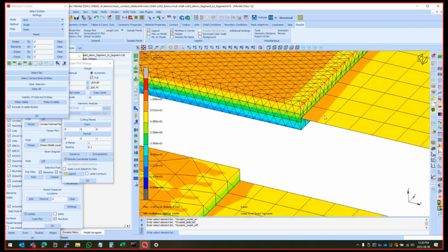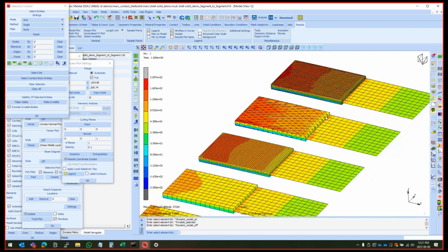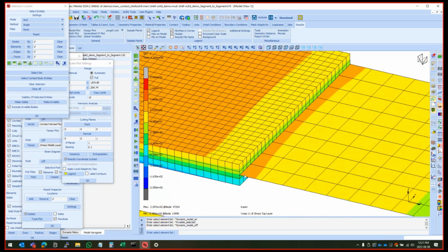For these second orders, I won't be able to create a second order skin there and merge with a first order. Even if it works, I'll get terrible answers. So directly connecting nodes for finer meshes simply does not work. So that means we have to use something like glued contact. If you use glued contact, again, it doesn't make too much sense to go from the coarse mesh on this side glued there. And unfortunately, that's exactly what I want to do.